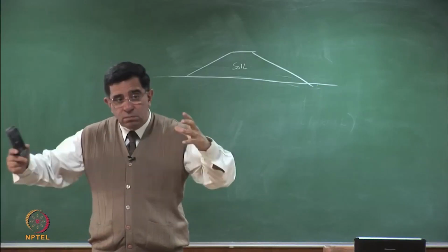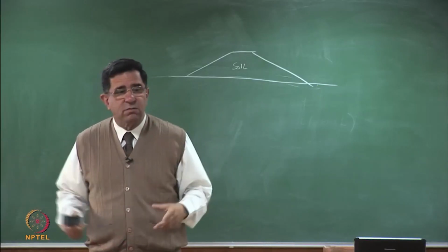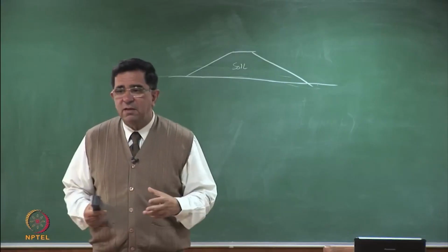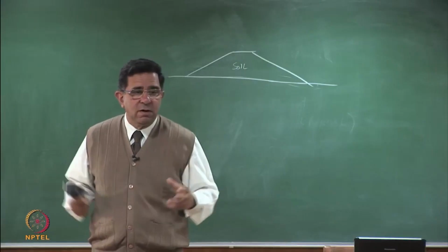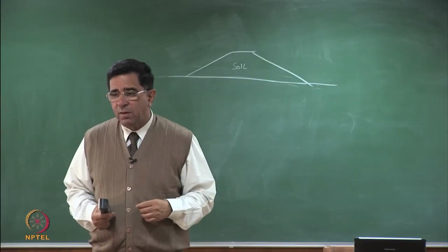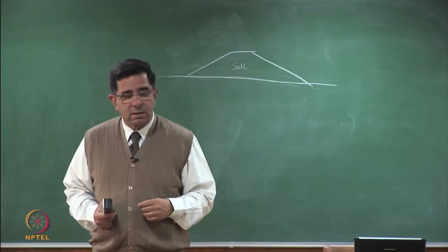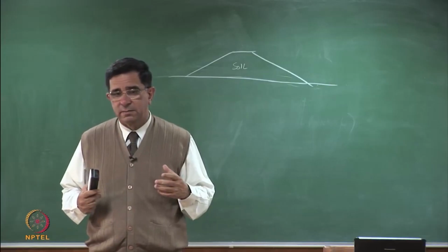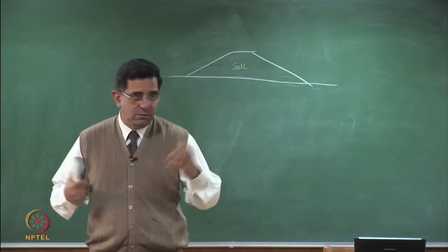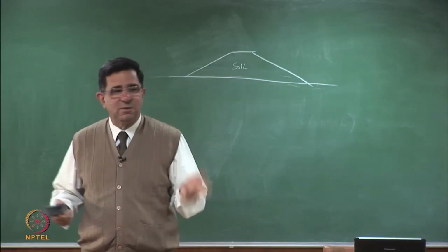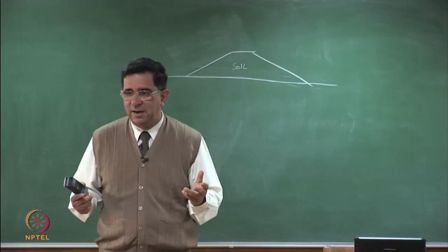If there are huge, large sized chunks of construction debris, remove them. What is large size? Anything which is beyond 300 mm, a foot in size. So remove them. And what is the parameter that you will determine? C, phi. C dash, phi dash. There is no other parameter, and if it's a drained test, you are probably getting C dash, phi dash.